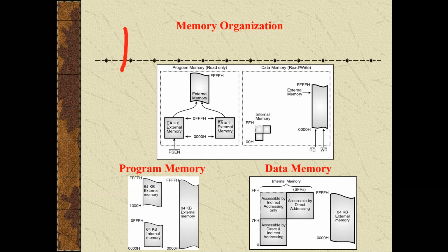So let's discuss while it is going to shut down automatically. See the memory organization here. In total there is 64 kilobytes of program memory and 64 kilobytes of data memory, and 128 bytes of internal data memory. Each memory has a separate addressing mechanism, different control signals and a different function. Each memory we access using a different mechanism. Let's see them one by one.